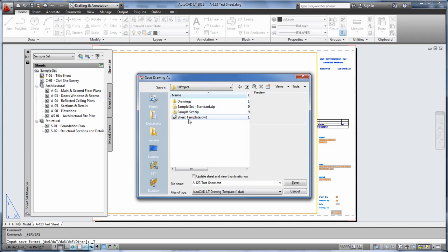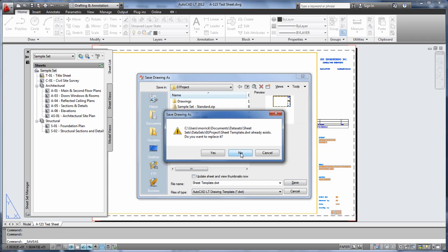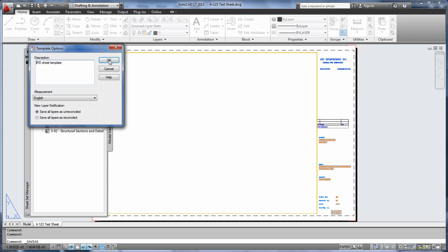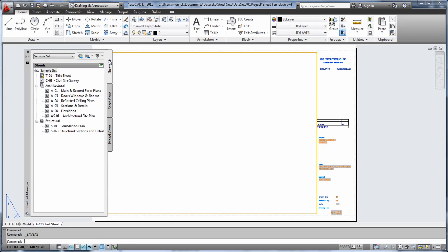This is the second reason why it's okay to put the fields directly in the attribute value. The title block already exists as an inserted block in the template, with data in its attributes, and you only have one title block per sheet. So when you create a new sheet, the information is already there in the block insertion. This doesn't work for callouts and labels, which have to have different information, like title and number, in every insertion.